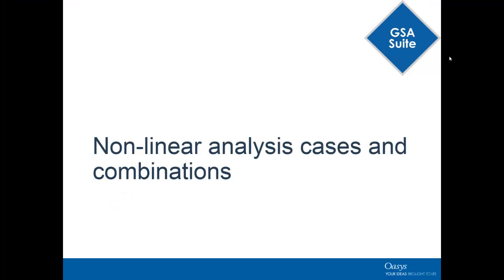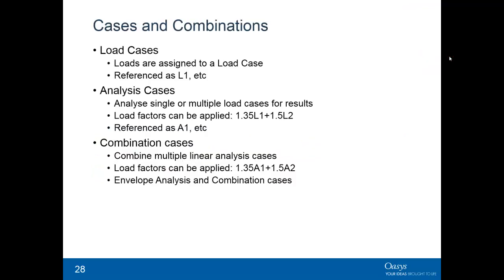Much about nonlinear cases and combinations, which I touched on earlier. If you're dealing with just linear analysis, you might not realize or spot that the load cases and analysis cases are actually separated. GSA by default will take the load cases where you apply the loads and create a single analysis case with the same name and the same number automatically when you just hit the analyze all button without defining an analysis case.